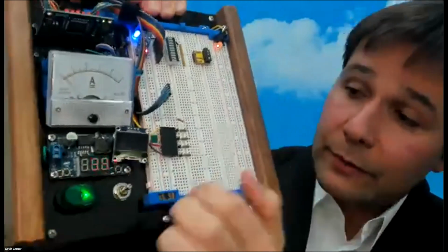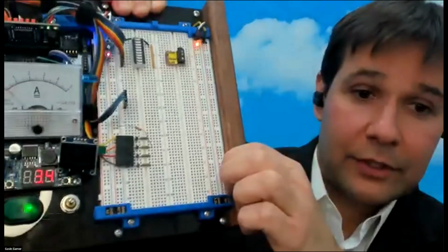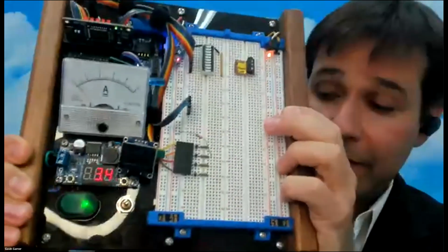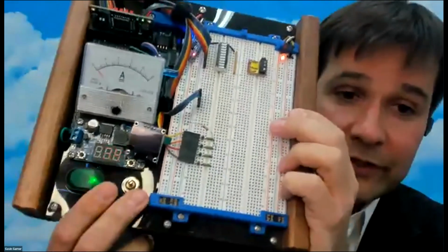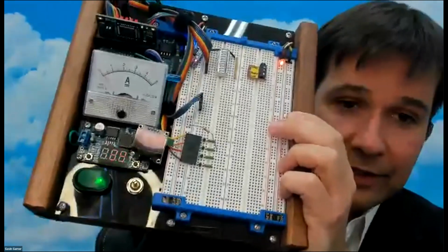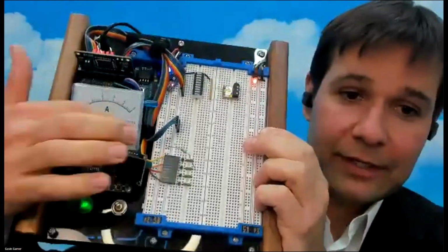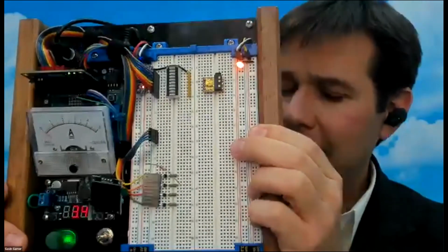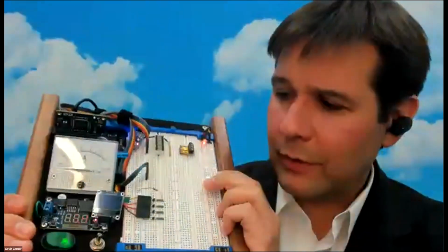And that goes into this strip of the breadboard under here. So it's a really convenient power supply, with the exception of the fact that you can't start up under load. For some reason, the way these things start up, if they've got any load on them, they'll kind of freak out and go to an avalanche current condition where this spikes and pretty soon a fuse will blow. So again, I'm not sure if it's going to be worth putting this into our kit, but it's been working pretty well on these.